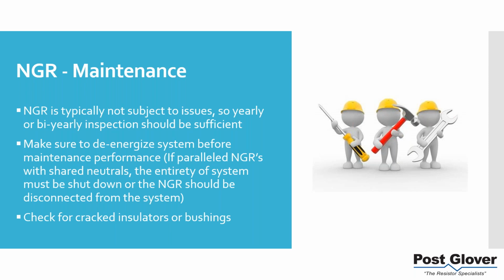Also look at, for example, dust. Typically, just regular dust is not an issue for resistance ground. Usually it would just burn off. I will say this, however: not all dust is created equal. I've been to pulp and paper installations where you open the cabinet and you see just piles of sawdust after 6 months. That's not going to be a great thing. So if you had that scenario, you'd probably want to clean it out every third or fourth month. But you would know that. If you're at a pulp and paper plant and you have all the sawdust everywhere, I'm thinking a lot of the outside equipment is going to have an issue like that.